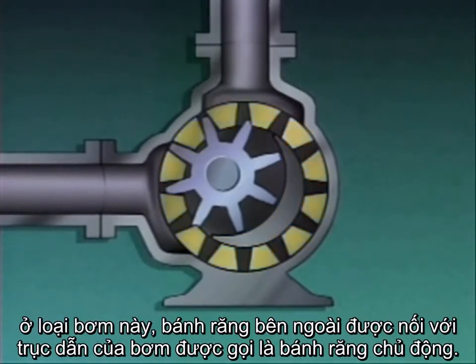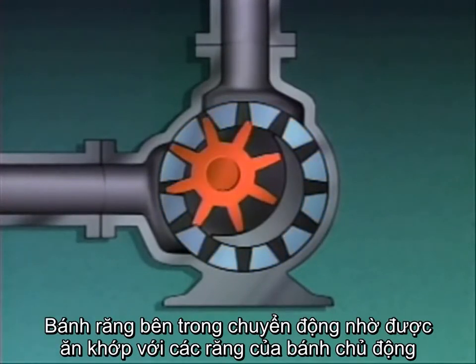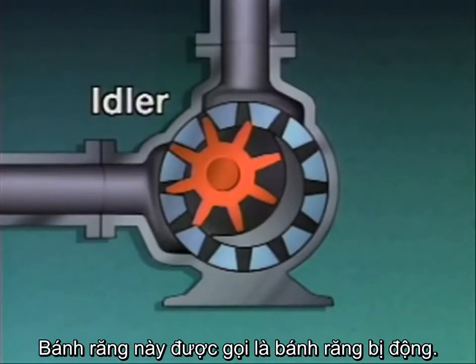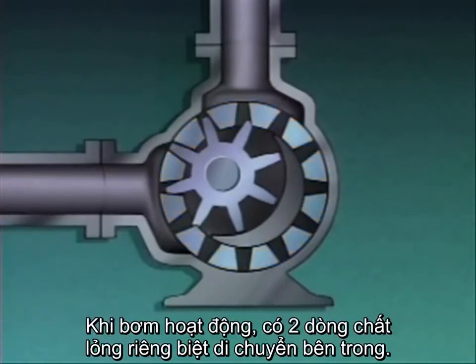On this pump, the outside gear is rotated by the pump's driver, so it's the power or driver gear. The inside gear moves because its teeth are meshed with the teeth of the driver gear, so it's the idler gear. But keep in mind that on some internal gear pumps, the inside gear is the driver and the outside gear is the idler. When this pump operates, there are two separate liquid flow paths inside the pump.